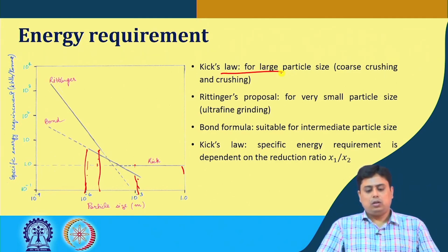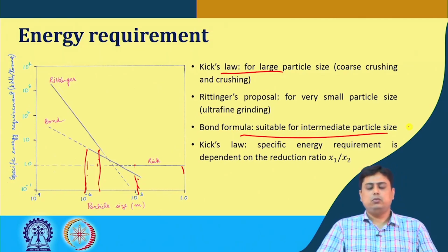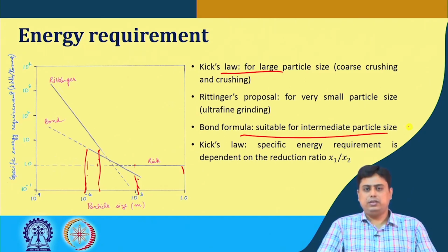And Bond's law, or Bond's formula, is suitable for intermediate particle size, which I mentioned earlier. This intermediate size is actually extensively used in industry applications, and that is why Bond's law is more popular than the other two.